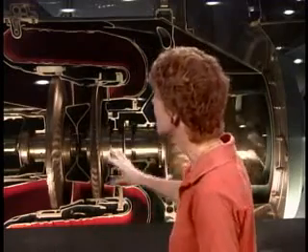The way they do that is they take high pressure, high volume bleed air and run it through this jet pump, and use that to pull in other air, a high volume of air under lower pressure. So the jet pump is used to augment the airflow, to get more airflow in some areas of the aircraft.